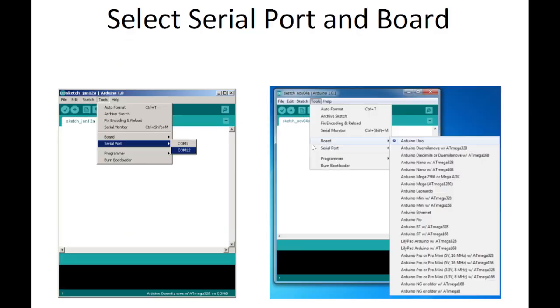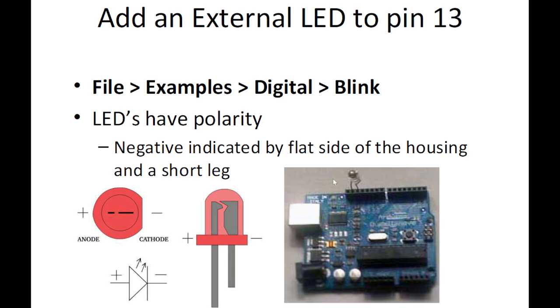So it's connecting the cathode side, which is this side, to the ground, and the anode to pin 13. And I can tell because of the notch, the edge here, this is the anode side, or the longer leg is the anode side of the LED, and that is going to connect with pin 13.